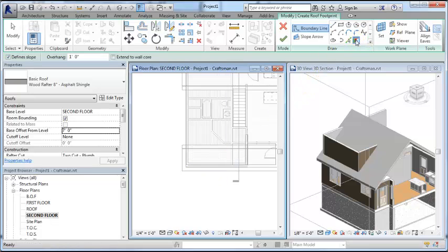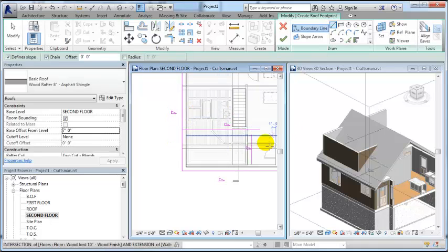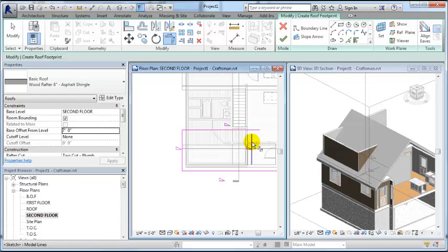And then to create the roof, I'm going to use the Pick Walls tool, and it's going to give me the same overhangs that I had set when I made the main roof. So I'll pick those walls. Now here's the trick to making a dormer. I don't want this back edge of this roof profile to go right up against the roof yet. I want to extend it to there. So I'm going to just use this Draw Line tool and draw a line across and then make connections to all of those pink lines. So these two should be filleted together. These two should be put together. These two should be put together.